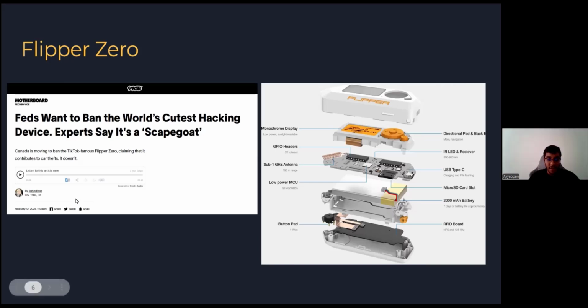Definitely, I agree 100%. And even with things like GPS spoofing, it's all right to do in a very controlled environment, usually a Faraday cage or an anechoic chamber where none of those signals are going to go out, because you just don't know the implications of it. There could be, I don't know, maybe a point of sale system that requires GPS time in order to actually do a transaction. And if you're spoofing GPS, the timing's messed up, and then transactions won't go through. It would cause harm to NTP and several other things.